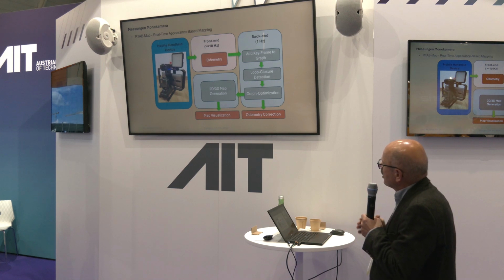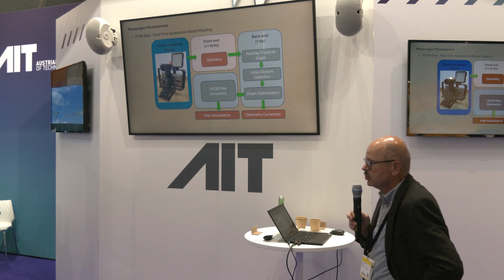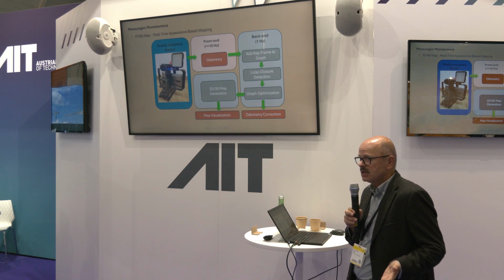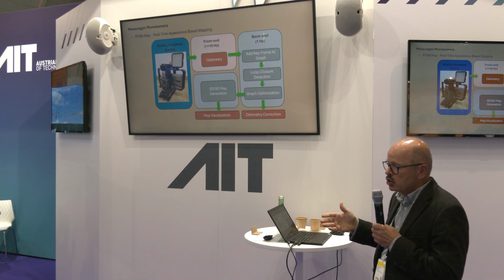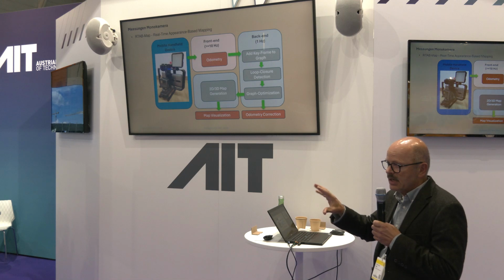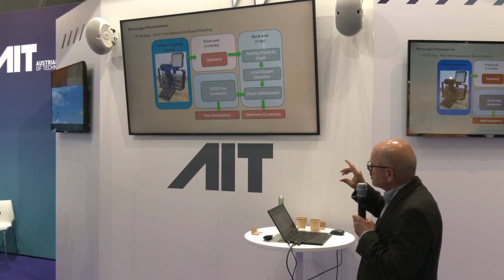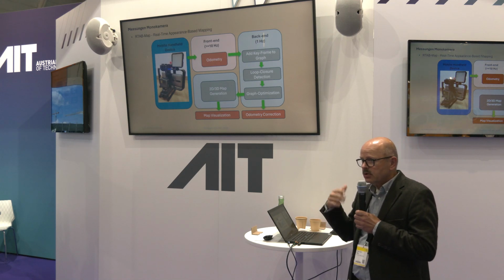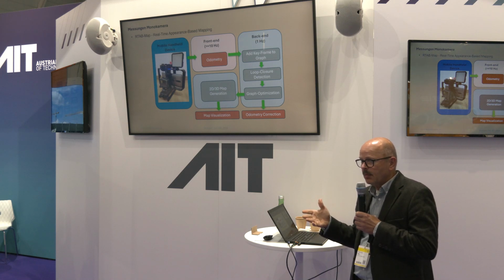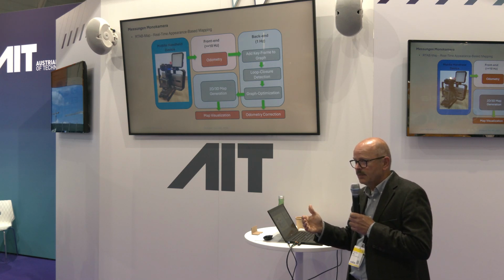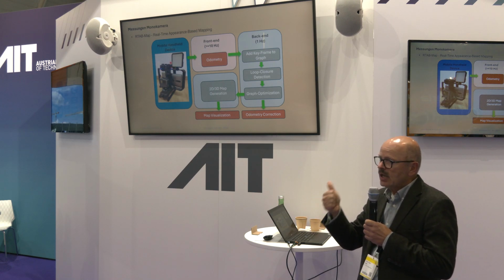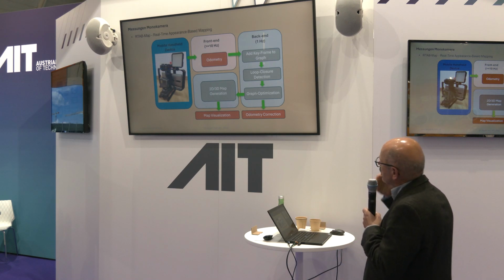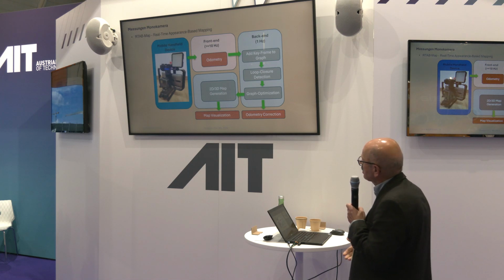It has a front end which does the odometry. It is 10 times a second. We get 3D information of one single place, because within the sensor we not only have the RGB camera, but also a depth camera, and for every single pixel we get the depth information and the color information. So this is done 10 times a second.